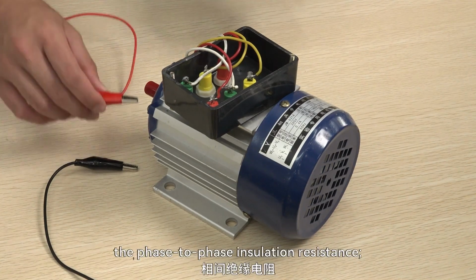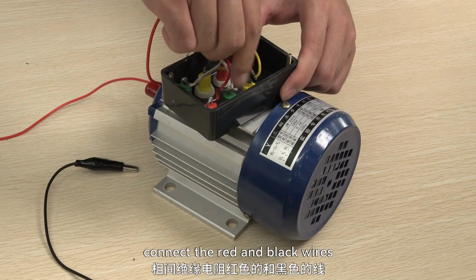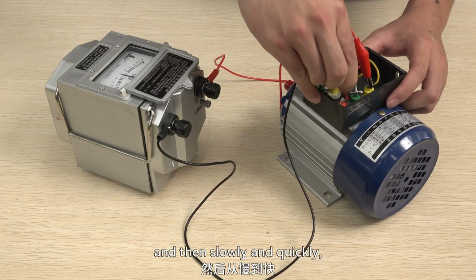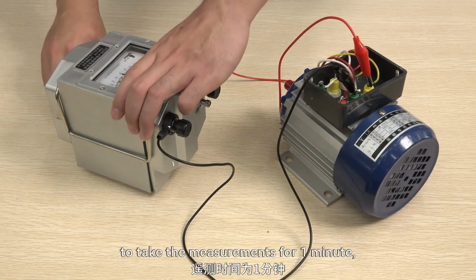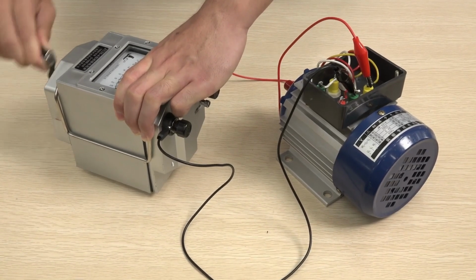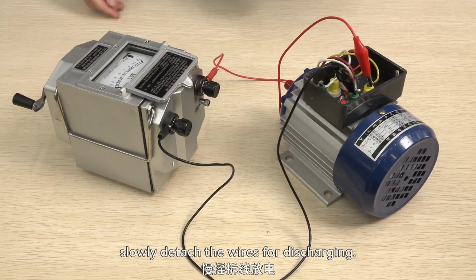Next, measure the phase-to-phase insulation resistance. Connect the red and black wires, or L and E terminals, to any two phases, and then slowly and then quickly, rotate the handle at 120 revolutions per minute to take the measurements for 1 minute, wait for the pointer to stabilize, and read while shaking. After reading, slowly detach the wires for discharging.